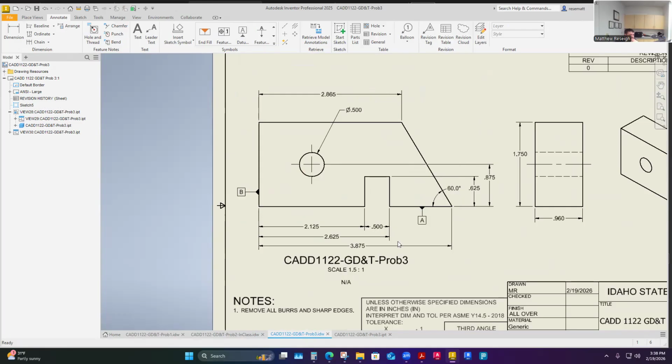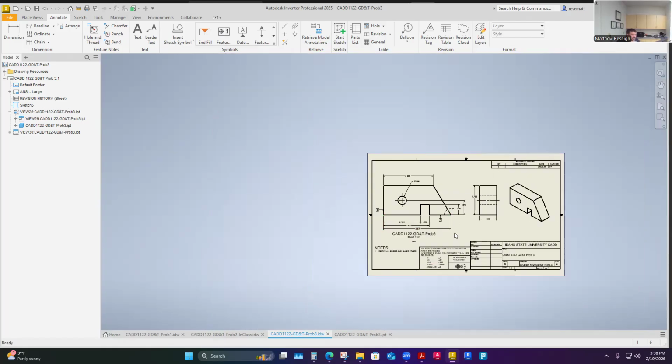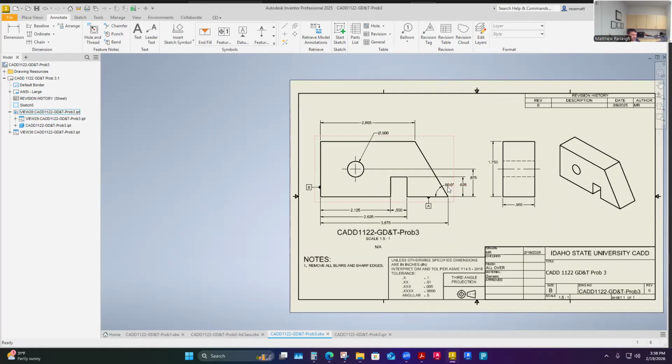Maybe before I move to the features of size, oh, the one thing I also did is I'm holding the same decimal equivalent of the drawing itself. I did change the decimal equivalent of the 60 degrees, and I guess it's just because it's going to become a basic dimension. So I could hold it to three.